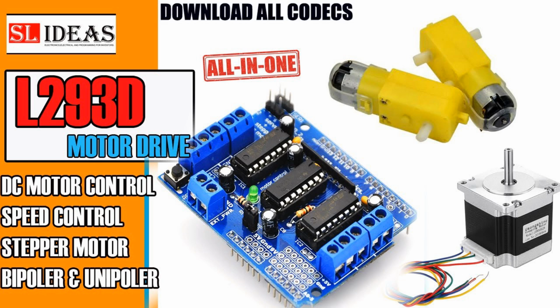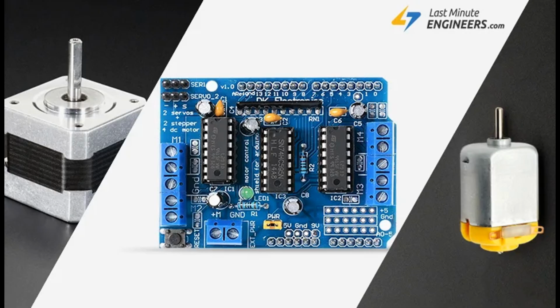2. Digital servo drivers. Function: digital servo drivers provide more advanced control features than basic PWM drivers. They offer higher resolution, better response times, and more advanced feedback mechanisms. Operation: these drivers often integrate digital signal processing, DSP, and microcontrollers to enhance performance. They provide finer resolution and smoother control over the motor's movement and may include built-in safety features like over-temperature protection and current limiting. Advantages: higher precision and faster response times.